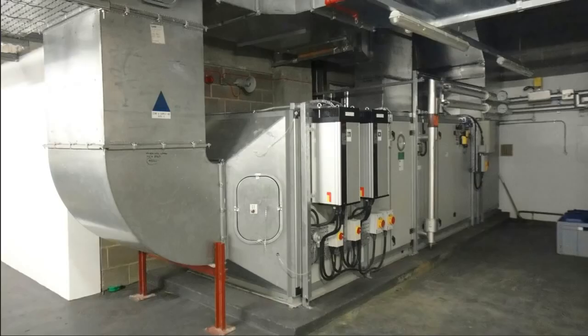The second AHU which you're going to look at, this is slightly different. It's only got a cooling coil on it. So the air's coming in here and it's being sent off again, off into the space. But you'll notice that this one has got some VFDs on it, some VSDs, variable speed drives or variable frequency drives, and they control the speed of the induction motor, which is connected to the fan.